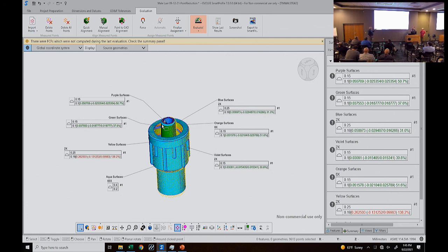And of course, that is traditional plus or minus tolerancing, which some people here who've been through a lot of GD&T training say, no plus or minus tolerancing. So we do that answer, but then we also do the profile answer, because the profile answer really gets at, will this thing work? And working here means not leaking.